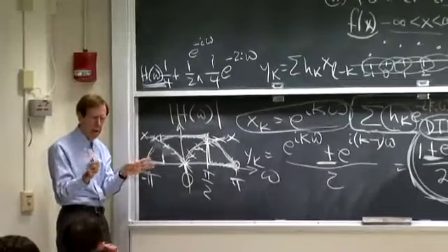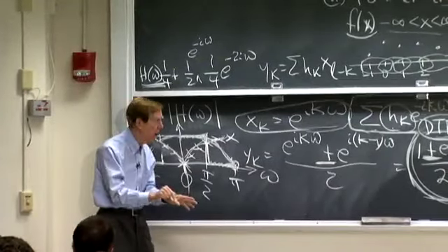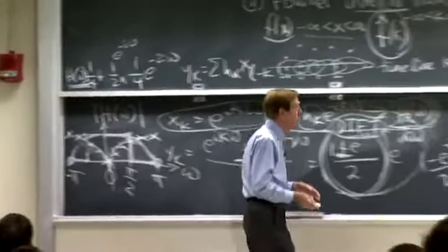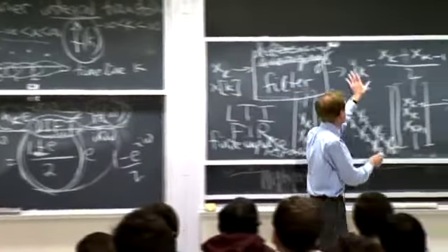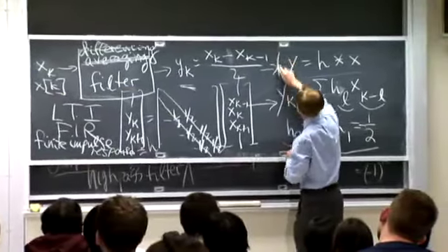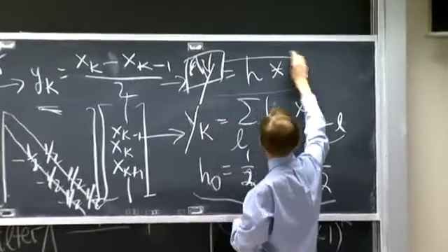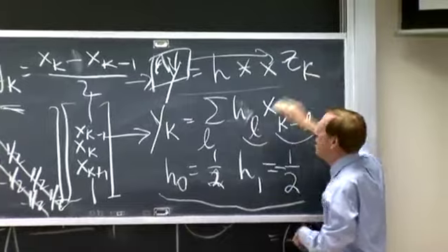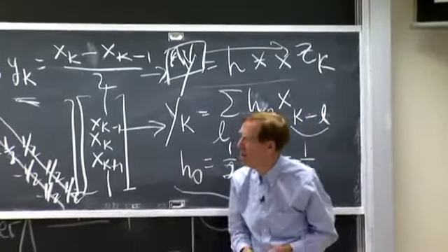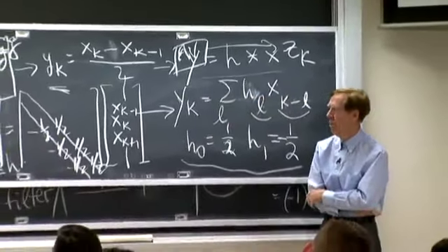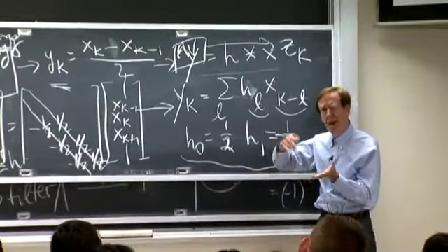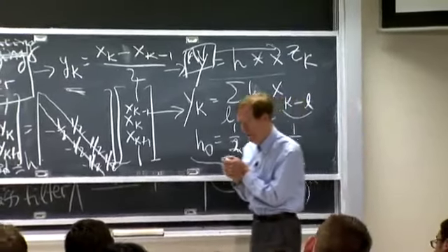If I do an average and then I do the average again, in other words, if I just send these signals yk through that same averaging filter, so average again, to get a zk, I think probably the coefficients would be 1/4, 1/2, 1/4, and I've taken out more noise, right?